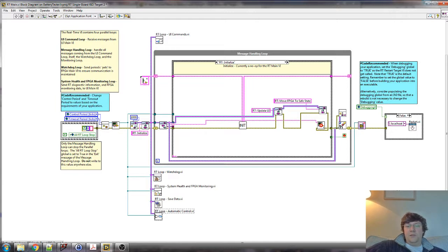You could have it, when the microprocessor comes back up, carry on where it left off, but I usually have it wait in order that I know it won't go straight to error again, and I can investigate that first error fully without having to wonder how the error stacked up and what went wrong. So it's better to wait and nail down your errors one at a time.